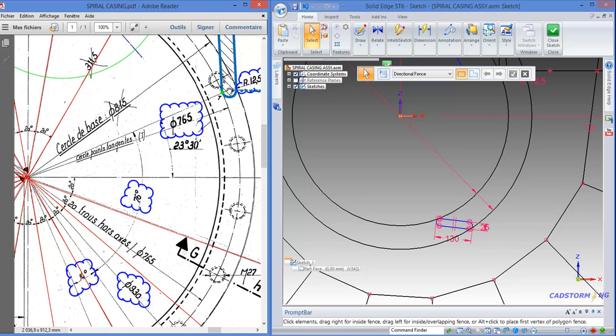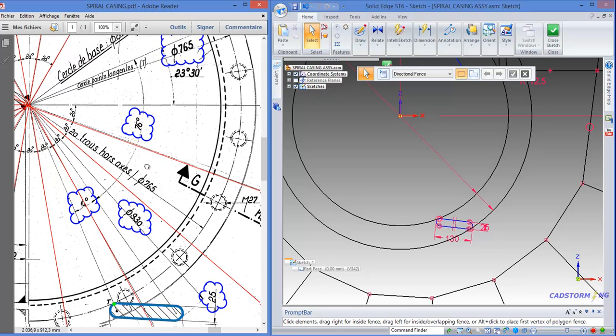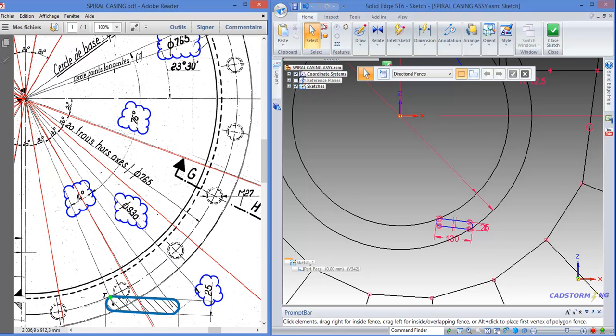The first line is starting from the center point of the arc for the first deflector to the origin, and then the second line should go from the origin to the center point of the first arc of the second deflector, and the 2 lines should be separated by a 76-degree angle, and we will have 14 degrees between the second line and the third line.